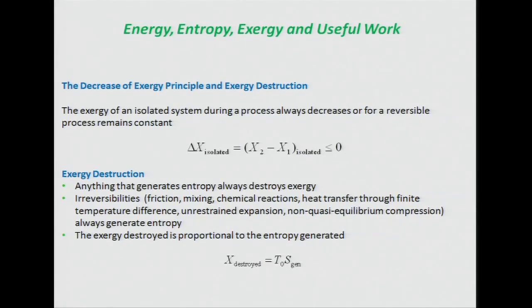Okay, so it's also true, because this is identical to the change in entropy rule for an isolated system, which can only be greater than or equal to 0 depending on whether the system is irreversible or reversible. So anything that generates entropy also destroys exergy. And so we found a very simple way of saying that. When we talk about entropy generation and we're concerned with losses and efficiencies in systems and processes that unnecessarily throw away perfectly good usable energy, we can identify that with entropy generation.